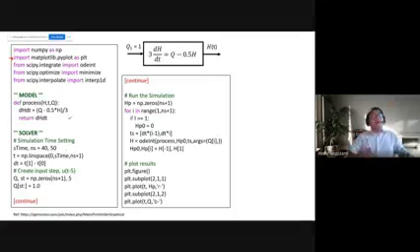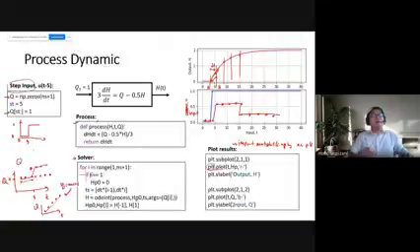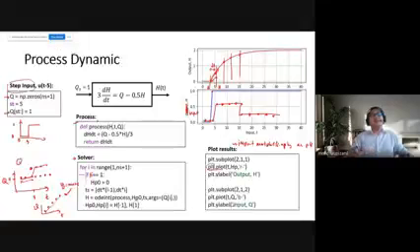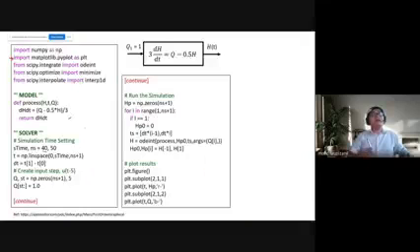If you look here, I don't include this in the solver because it is not important for the process dynamic, but it is important in the syntax to run the program. This is just a definition for simulation time. I want to run from 0 to 40, which is the end of simulation, and then the number of samples per graph. When I generate a plot, how many points do I want? In this case, I just get 50, meaning the interval is 40 divided by 50.